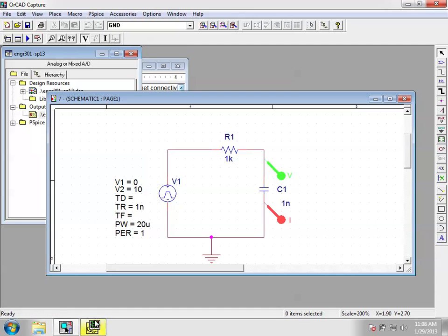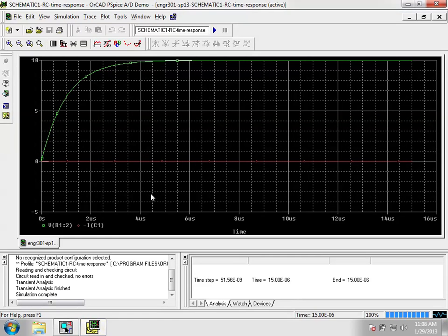So I say run, I go over here, both the probes lit up, notice, and I come over here, and see, that's kind of what I don't like about that, is that the voltage scale, whatever takes up the larger unit scale, dominates the response graph. There's lots of data happening here, but it is unobservable because it's so small. It's 1,000 times smaller, right?